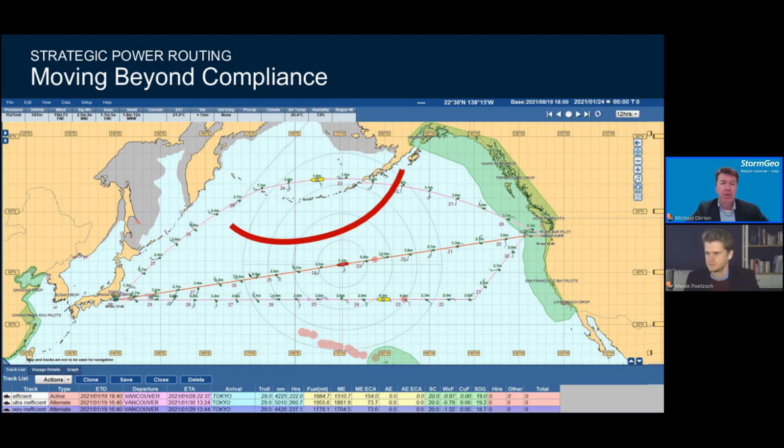And why is that? This red line from west to east is representing a typical pattern in the wintertime, where you have low pressure centers tracking to the south of the Aleutian Islands. That northern route is passing north of that, and you tend to get more time of following conditions, less head weather. Conversely, on those southern routes that are longer and to the south of the low track, you're actually putting the vessel into areas of more prolonged southwest, northwest wind conditions and heavier northwest swells.